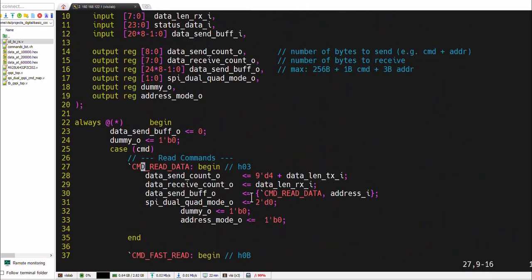Okay, 03. In that we have to send 4 bytes, so the send count output will be 4, meaning the length of sending data is 4, and if we are sending anything additional, there will be the data length plus that.